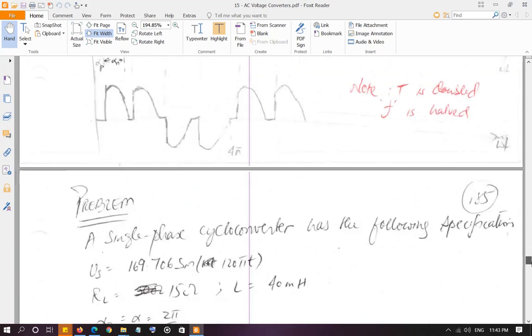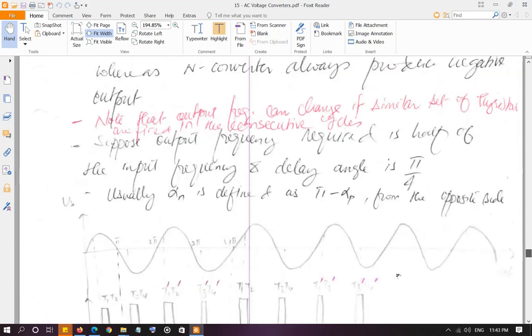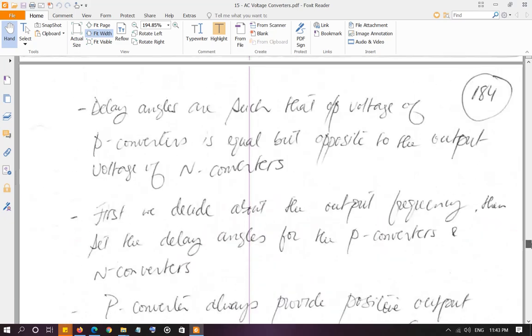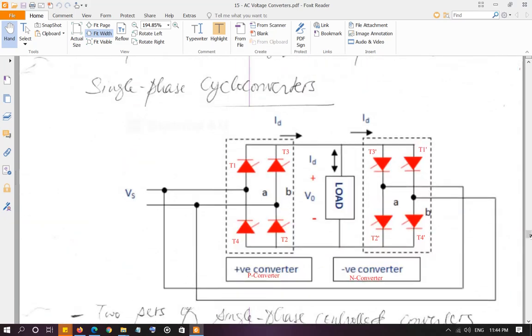Let's go to this waveform. So positive cycle when it is fired is here, and the negative cycle when it is fired, it flipped over because the current was flowing from top to bottom, right? Okay, so both cycles become positive. The first cycle was positive, but the negative cycle became positive as well.